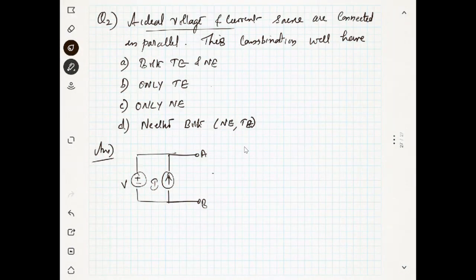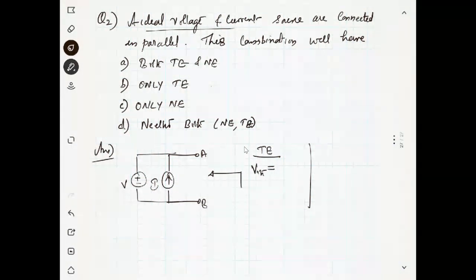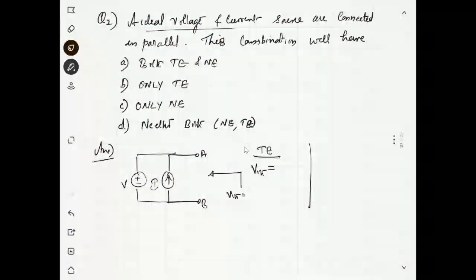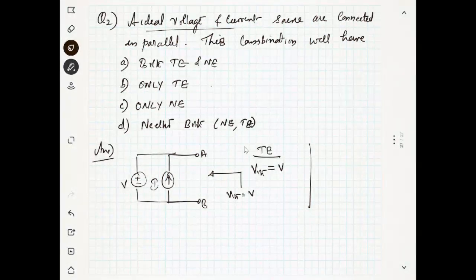So if you see from here, you are going to find the Thevenin's equivalent. First of all, we will try to find the Thevenin's equivalent. How to find it? We want to find V Thevenin. If you see from here, what will V Thevenin be equal to? Same as the voltage source. Yes, it is the same as the voltage source.